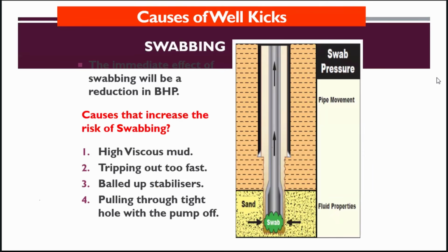Then swabbing, I explained. Swabbing is opposite of surging. When you are going up too quickly, this acts like a piston. This bit acts like a piston and it swabs in any gas which is present in the formation.